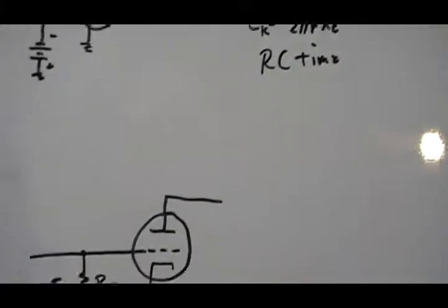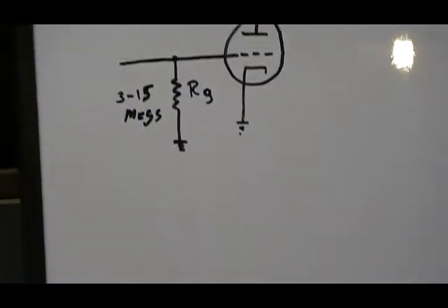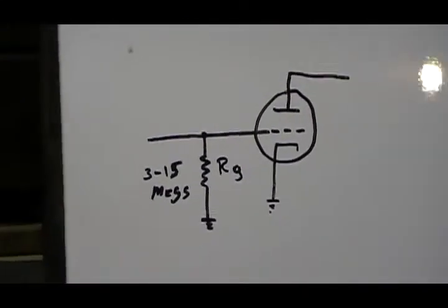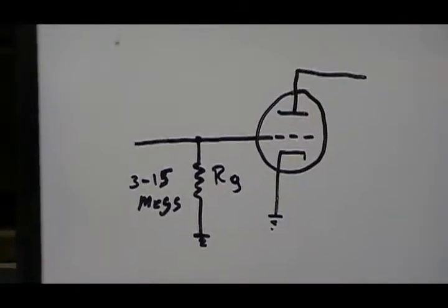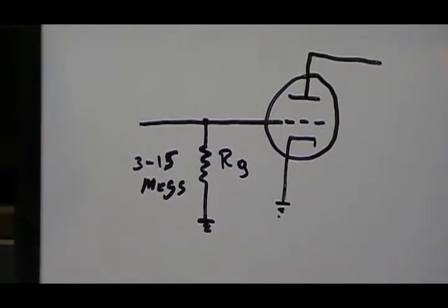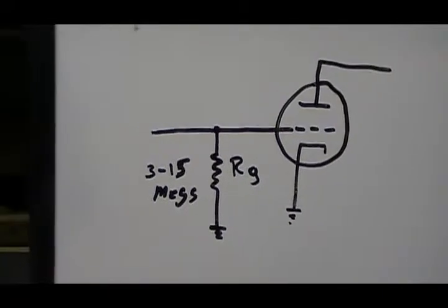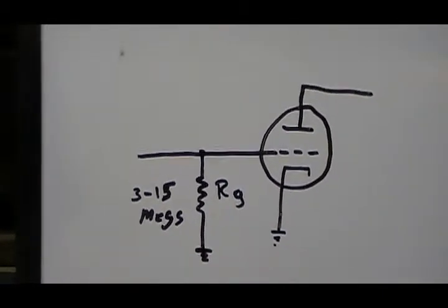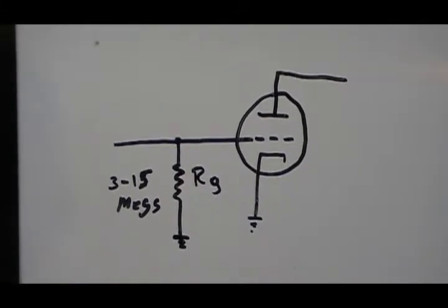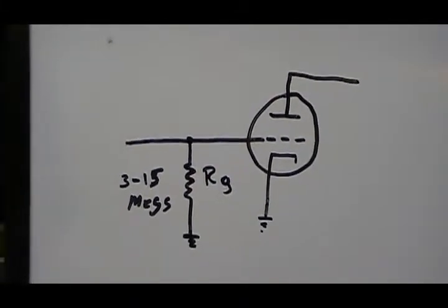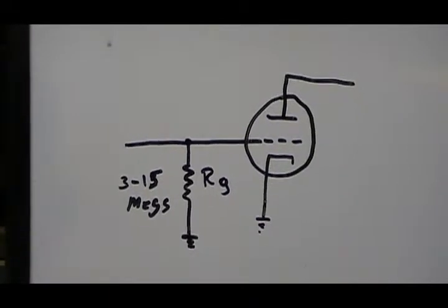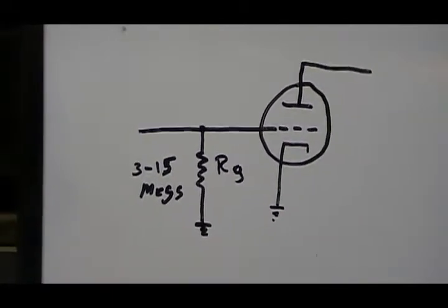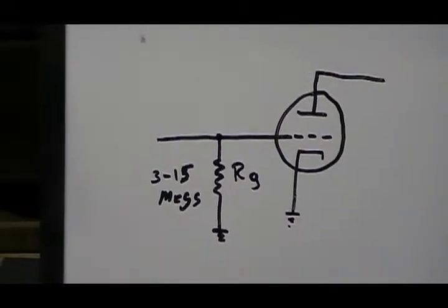One last one that's used tremendously with certain tubes and more newer radios, things like the 6SQ7 and I think the 6AT6, and there's a few others, is what is known as contact bias. And if you're not sure what 6SQ7 is, that's the dual triode or dual diode triode tube. It's the detector with the first audio.